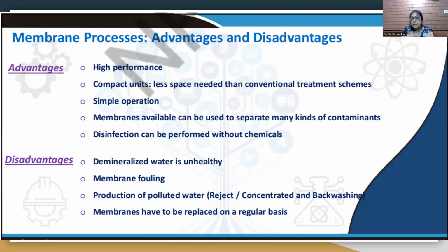It is also demineralizing water. It is also resulting in the removal of certain minerals in water that are useful for us. So that is one disadvantage of it. Not only that, these membranes over time are going to be collecting all these contaminants, and it will result in a process called fouling, which is resulting because of the accumulation of the contaminants. So it also needs to be replaced on a regular basis. So that is another disadvantage of this membrane-based process.